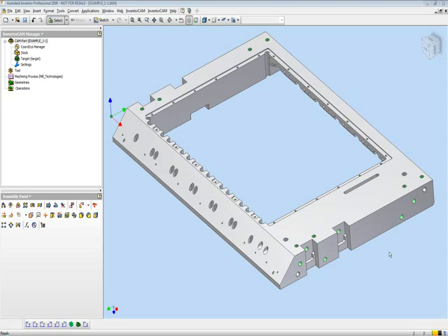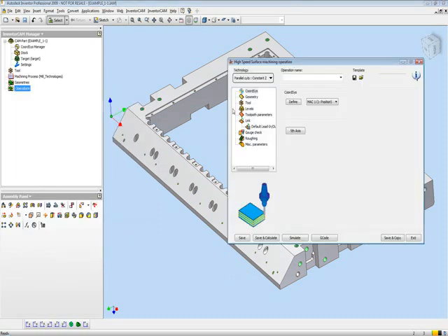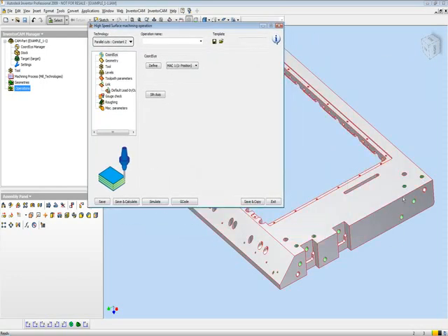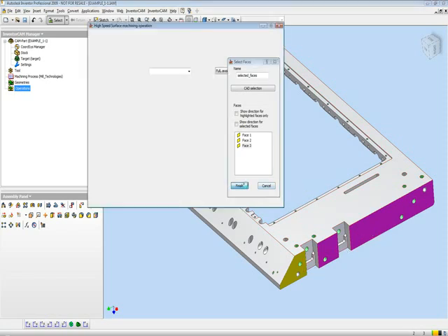But in HSS we have the tools to actually allow us to glide over this area as if this was one whole complete surface. Now I'll start my operation in HSS using the option of parallel cuts, constant Z. In other words, I'll be working on these surfaces parallel to them in the constant Z fashion on the surface itself. My geometry will be this surface, and this surface as shown here. Notice again, as I've mentioned before, there are gaps between the surfaces plus the holes on the surface itself.